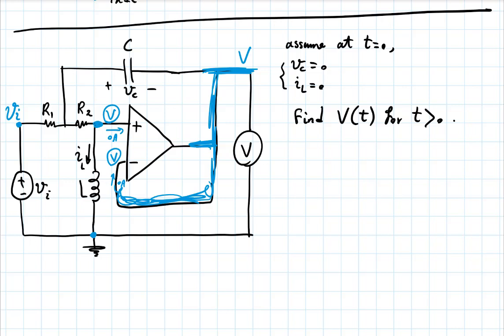I'll make a few observations and write down equations. And I'm doing this, you might say, more or less in the spirit of nodal analysis. So I have a node voltage here, Vi, another node voltage here, let's call it V1, maybe. I have V here and here, so that's all written out. And I think I have all the node voltages. So let me start writing things down. For instance, this current, if I call this I1,